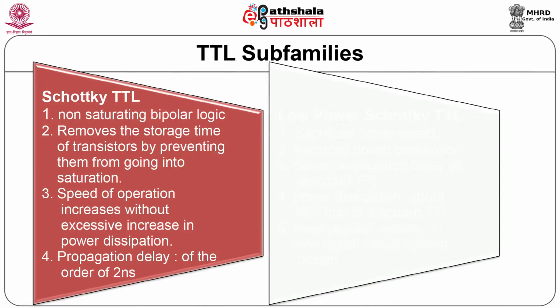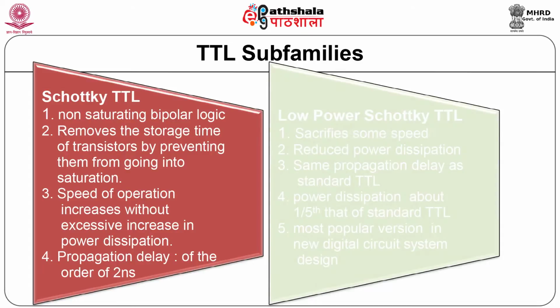In Schottky TTL, non-saturating bipolar logic is used. It removes the storage time of transistors by preventing them from going into full saturation. Speed of operation increases without excessive increase in the power dissipation. Propagation delay is of the order of 2 nanoseconds.